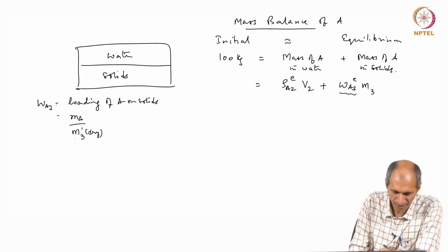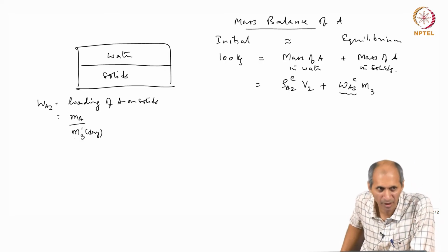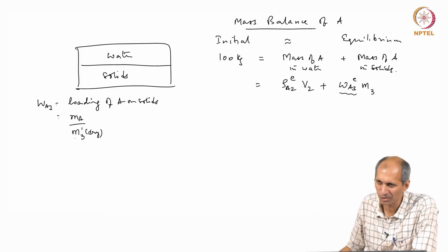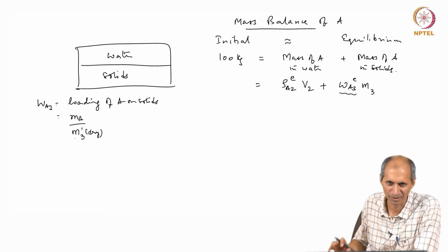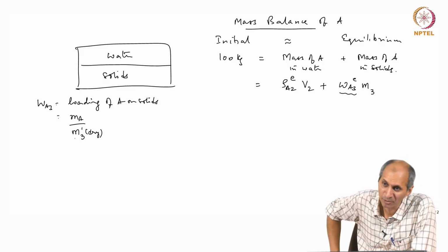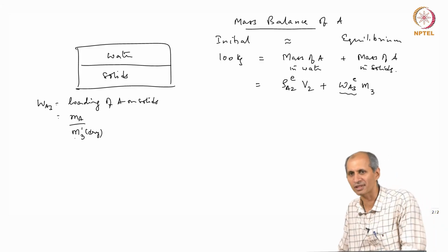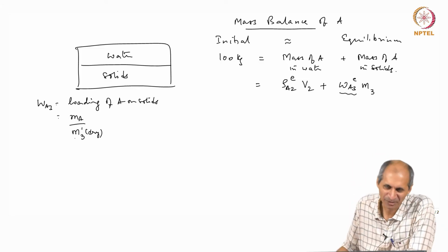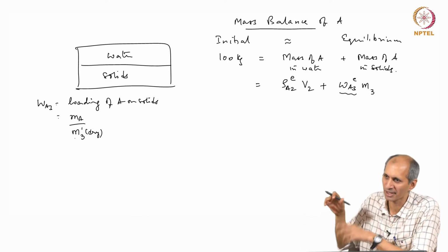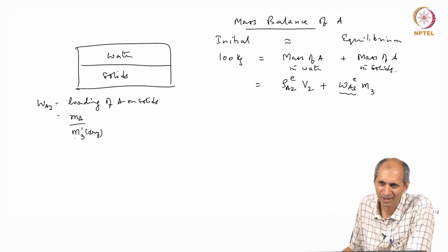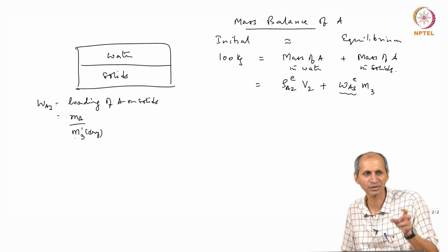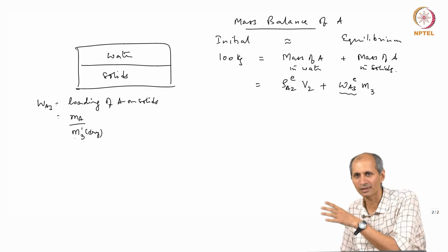So, for that reason it is convenient for us to use dry mass, which is why people also use it for moisture content, but sometimes it is convenient to use wet. So, this problem is complicated because of that. Also, when you use dry mass moisture content basis, the fraction goes beyond 100%, because you can have more water than solid. It is very nice when we express moisture content as a fraction, with an upper bound of 1.